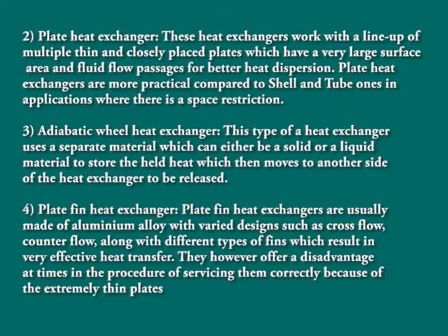The fourth one is the plate fin heat exchanger, usually made of aluminium alloys with varied designs such as cross flow and counter flow, along with different types of fins, which result in very effective heat transfer. They, however, offer a disadvantage at times in servicing them correctly because of the extremely thin plates.